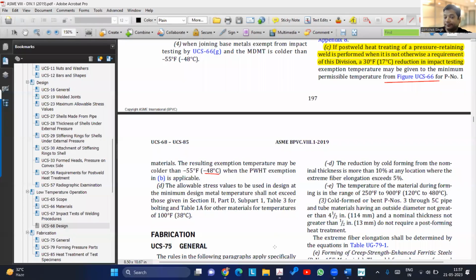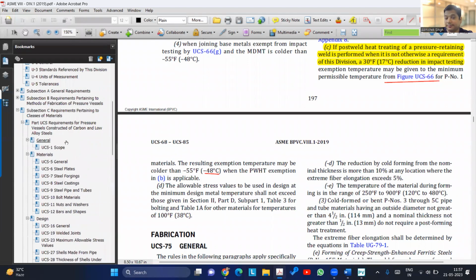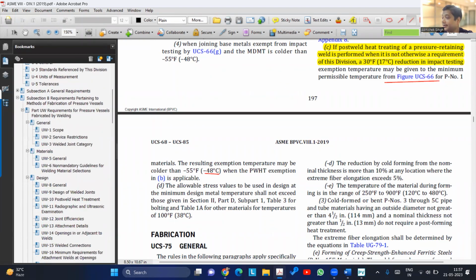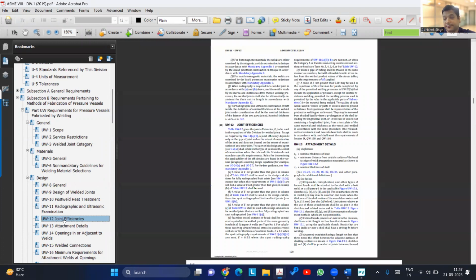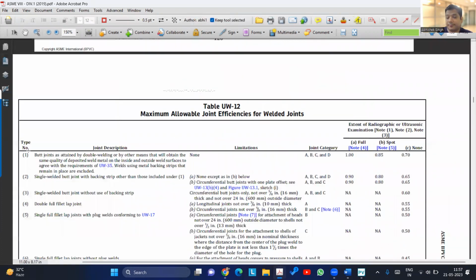Yes. But in our case, there is no long seam. It's seamless, but let us see, if a seam is there, then it's joint efficiency 1 for full radiography. For a type 2 joint, see here, 0.9. For this seam, the backing ring remains in place. For the case you have indicated, that is not valid, but just for knowledge, we are sharing. So for a type 2 joint, it will be 0.9.